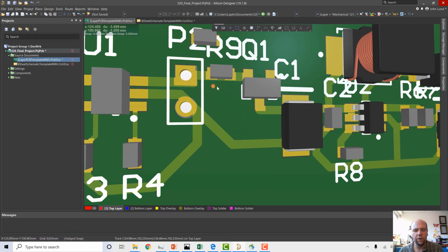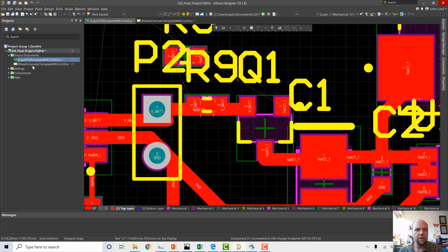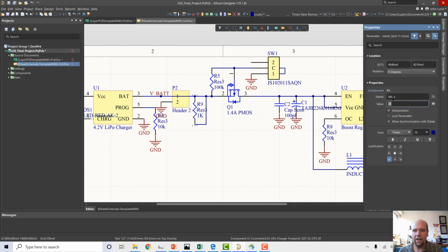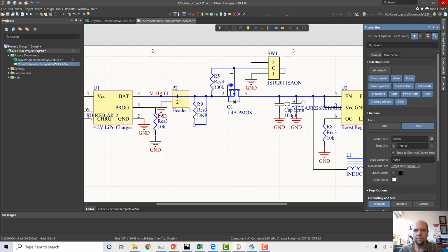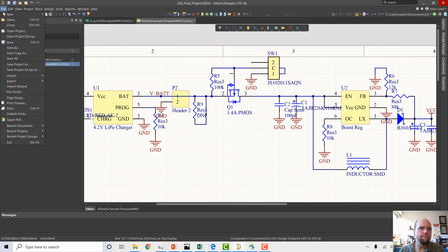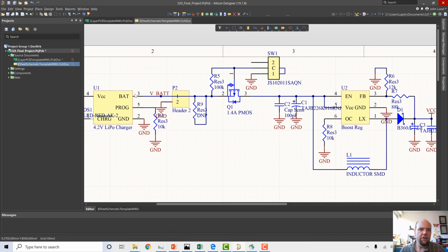Now we want to specify, it's a little weird to put this in the design. So one thing we like to do with these usually is, for the value here, I'm going to put DNP. This is just an indicator, looking at this schematic, that you shouldn't populate this. This is just a footprint that's there for our use. Maybe we need to populate it if we end up doing something, but it tells whoever's assembling this, look, you're not going to actually be putting something there when you build the board. Okay, and we can leave that in there and that's all fine.